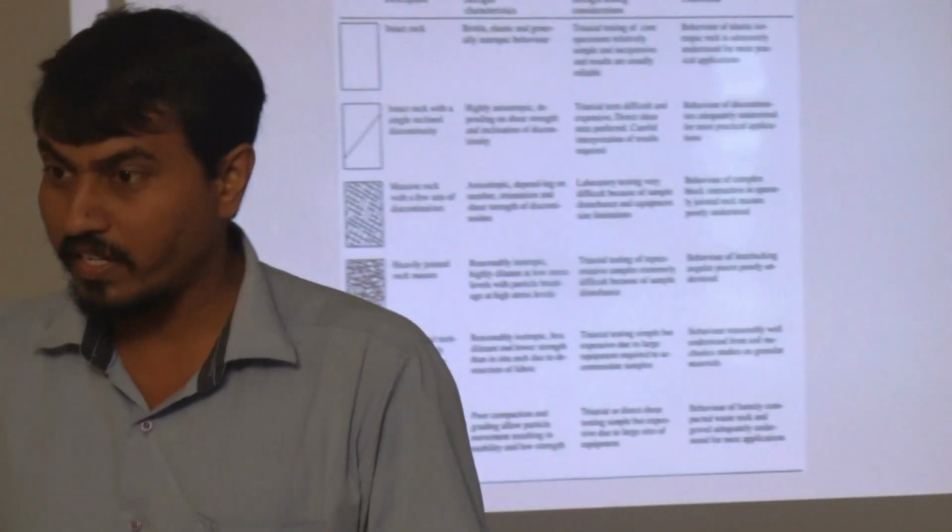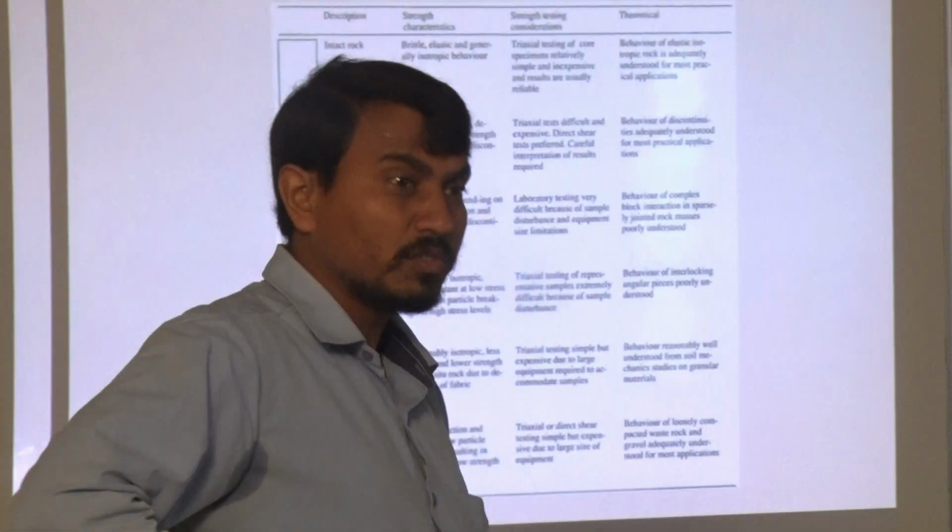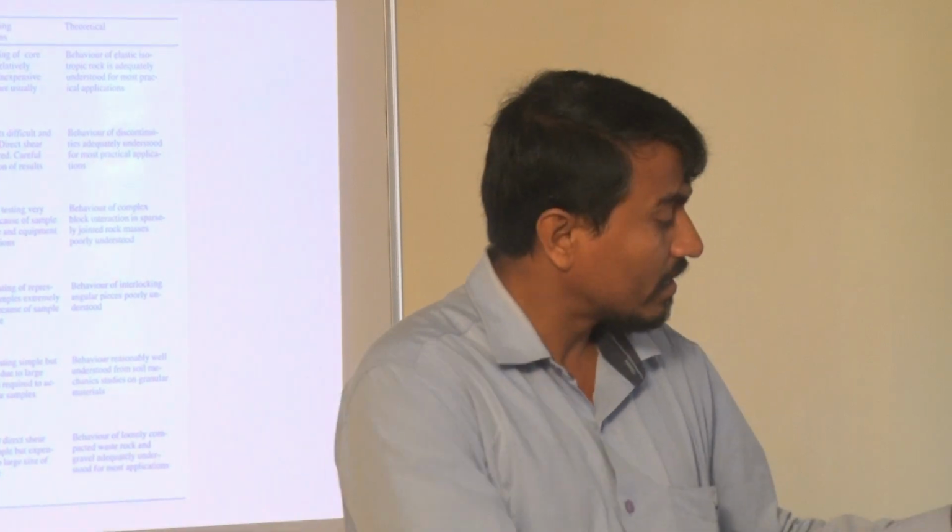For a homogeneous rock, suppose a very good quality graded limestone, if you test it for uniaxial compressive strength or triaxial, from the result all engineers can tell whether the graph is correct or not. Because we know the characteristics of the intact rock, which up to a certain limit behave elastically. So that is the advantage.